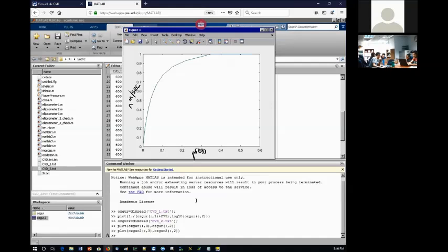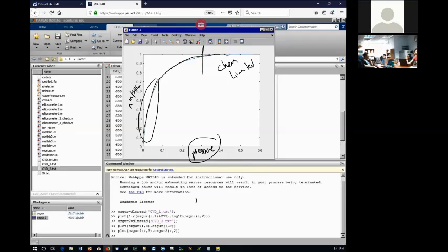We're flowing in different levels of silane into the chamber. What's happening? Well, initially, we are adsorption limited, so we don't have particles so much yet. So it's diffusion limited. Later on, it becomes chemically reactive limited. So here, it becomes chem limited. Even though we offer more silane, it does not react quickly. Here, we offer silane and it reacts immediately. So this is the diffusion limited portion.